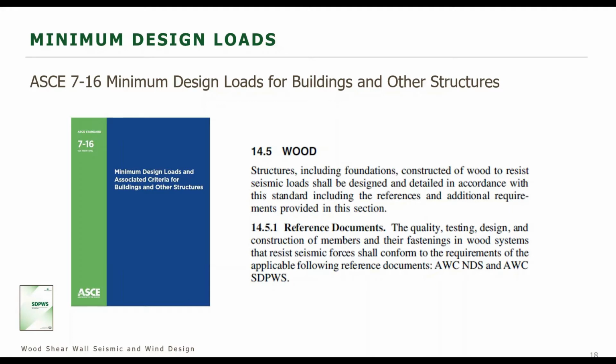A key portion of the ASCE 7 is chapter 14, which contains reference documents, and you can see the text here shows the reference documents for wood in the ASCE 7-16. So SDPWS is included in that reference in 14.5.1 there.